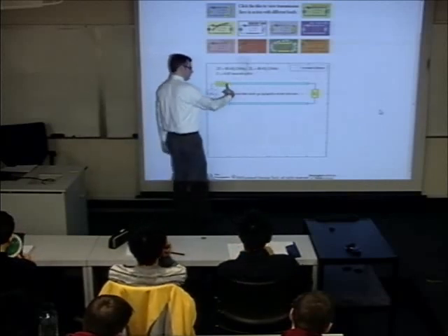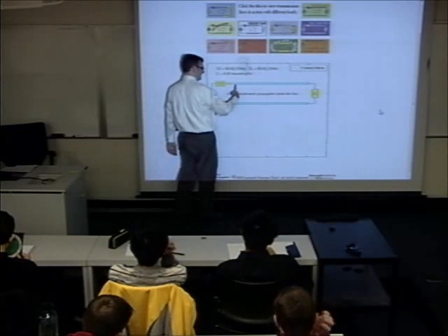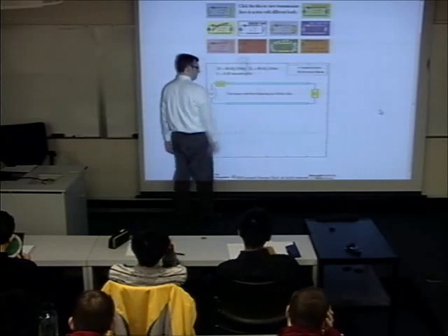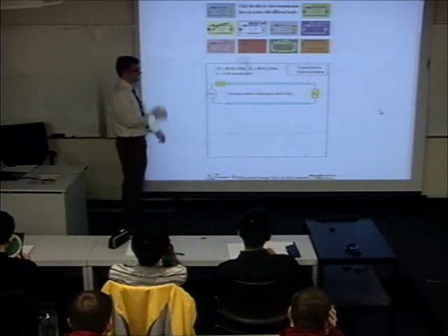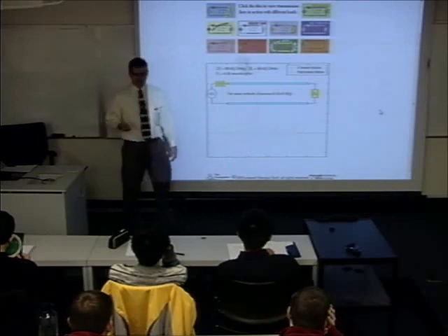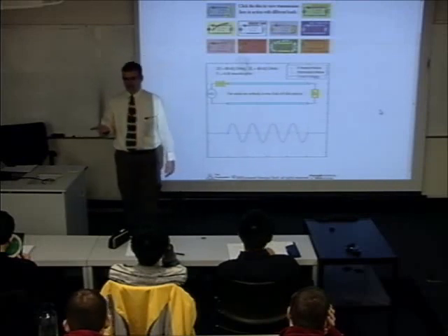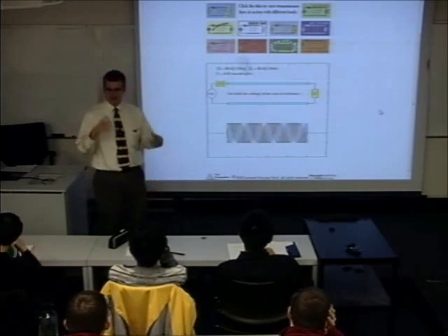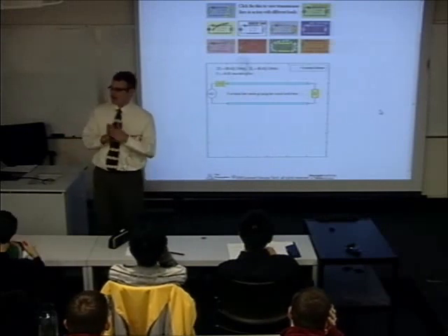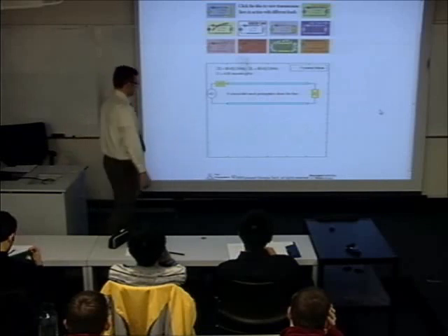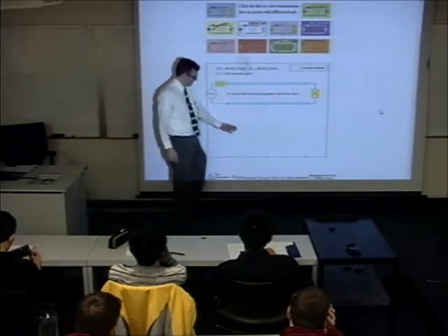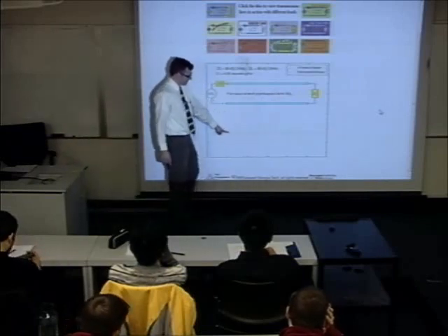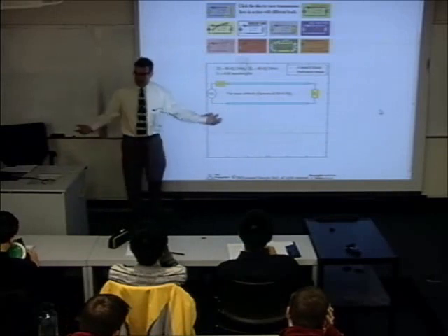What you would observe if you took an oscilloscope or a voltmeter and put it down the line. Now, this first case is the trivial case, where you have a perfect match. So in this case, 50 ohm transmission line, 50 ohm load. You'll see this green wave, the forward traveling wave. The red wave is the backward traveling wave, but it's zero because it's a match.